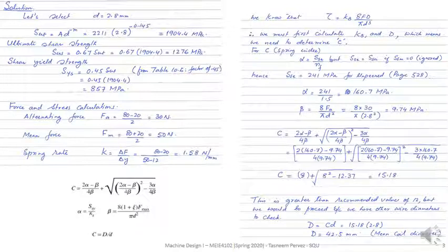If you remember, the spring wire diameters that are available start from 1.7 and go up to 2.8 millimeter. So I had chosen the maximum one. You can choose the smaller one because we have to do the calculation for each one of them: 1.7, 1.8, 2.0, 2.15, and so on.